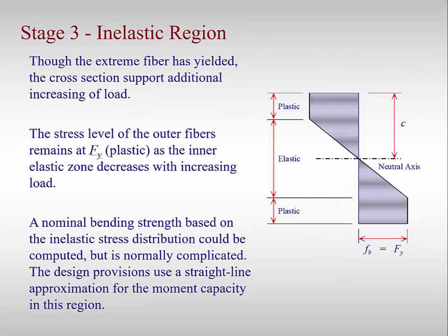Now, it is important to realize that, again, just because there is yielding somewhere on the cross section, it doesn't mean that the beam has reached the limit of its load carrying capacity. The load can be increased further since the inelastic regions can still resist additional stress levels.